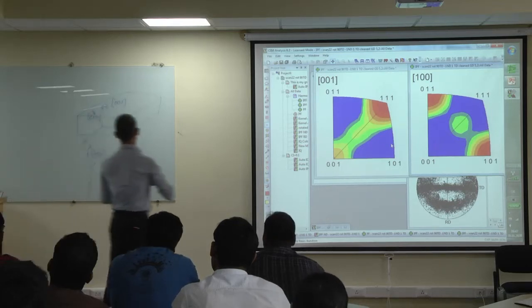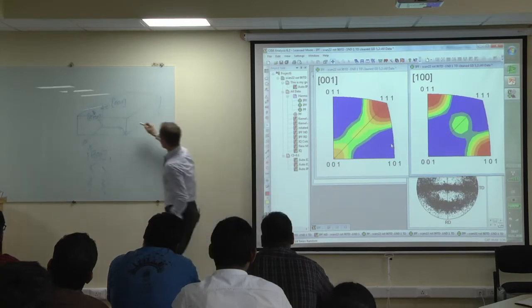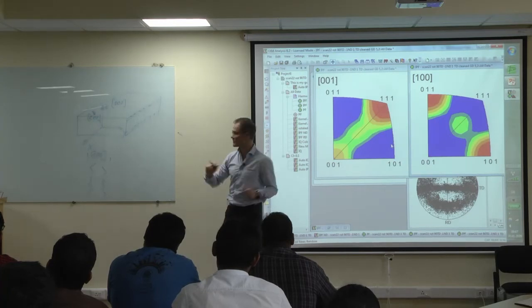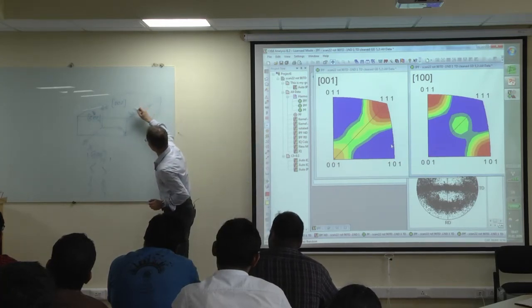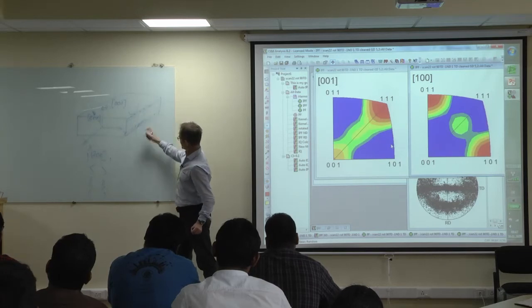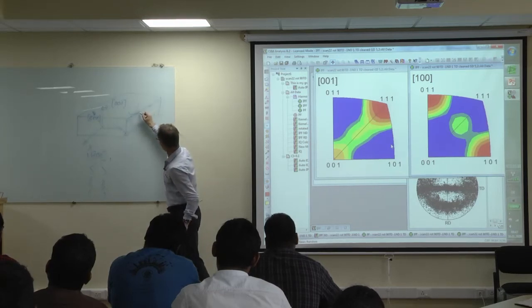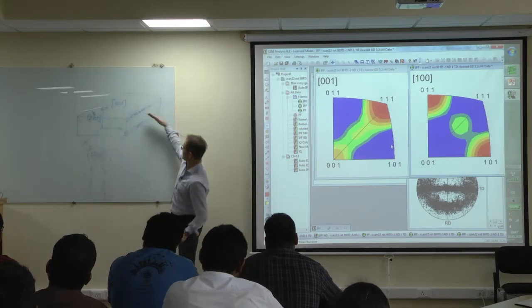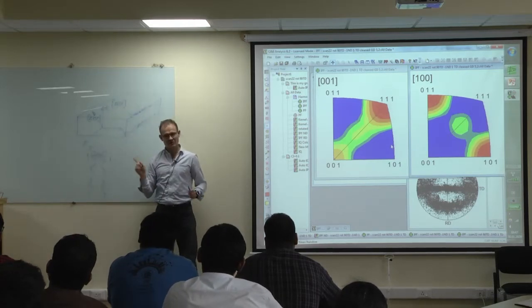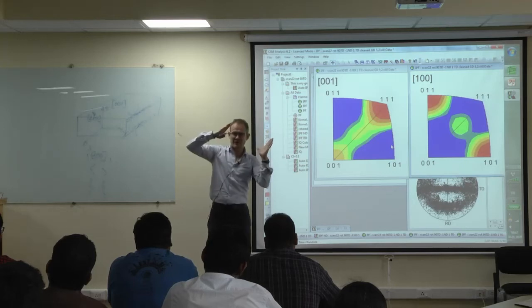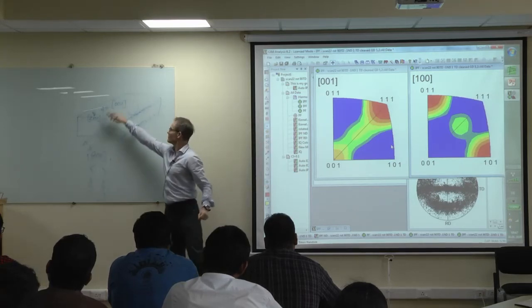But even in a rolled material, you remember perhaps from yesterday, I showed you that the surface has a different texture than the center. Surface like that, and center like that. And now the surface has, of course, experienced the action of the rolling cylinder. So here was the rolling, and that means there is some shear going on when you're on the bottom, and some shear when you are on the top. And this shear action is no longer going in the direction Z, but at an inclination angle. And in order to see that properly, it's better to select a plot direction where I'm looking under a certain angle rather than exactly under Z, X, and Y.